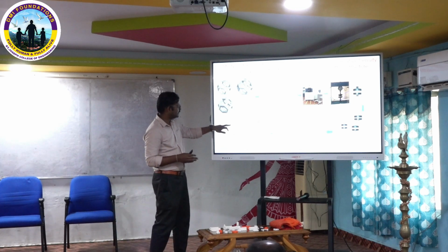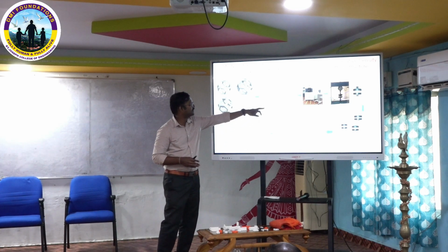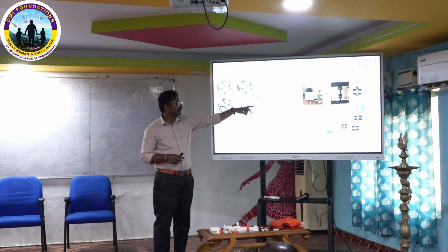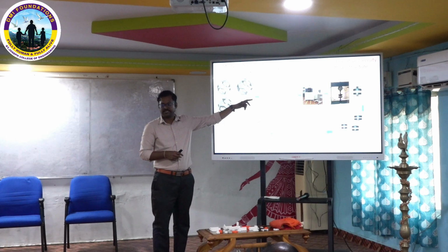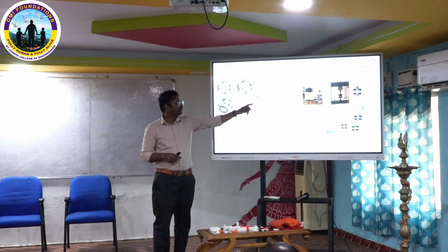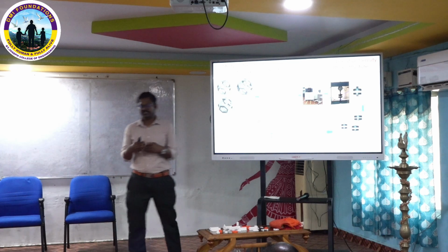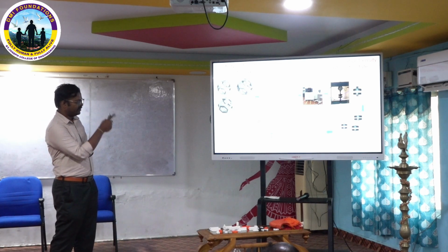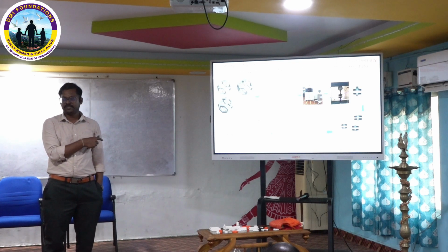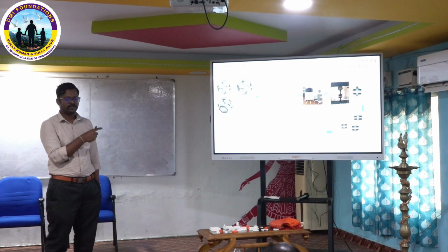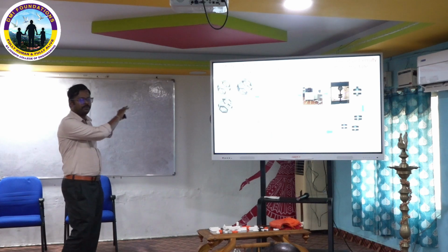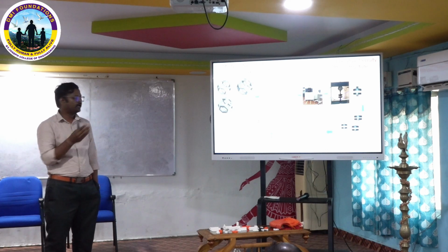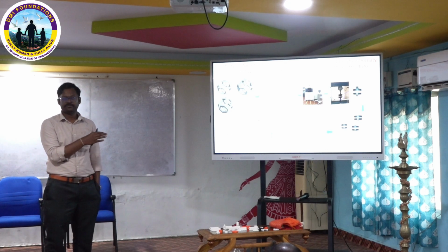So I take these three properties, and I added relative density for that. Then I fabricate, I do Taguchi analysis, DOE. I fabricate the part and test it with a compression test, UTM. Then I get the stress strain curve, which I showed there. First portion is the linear elastic region, second one is the plateau region. Since it is a bending dominated structure, I get only a smooth plateau region. So the energy absorption will be good there.